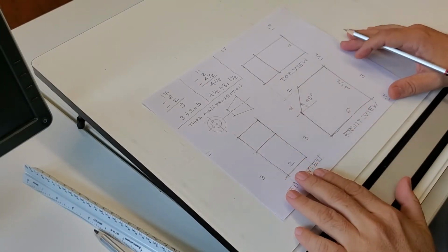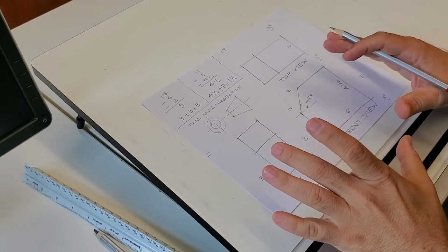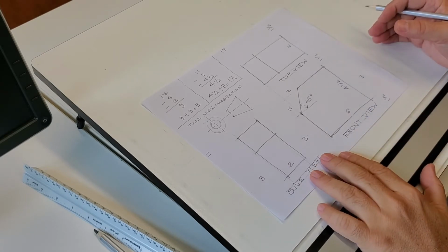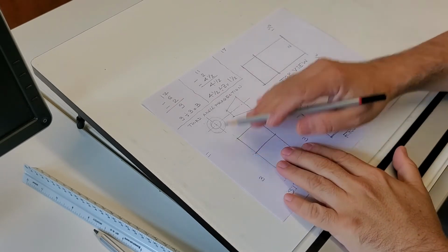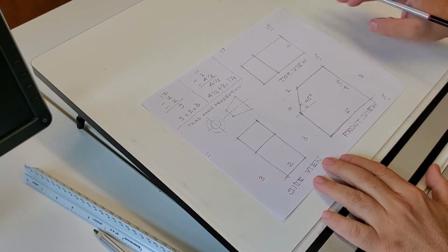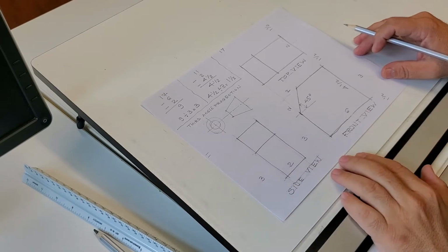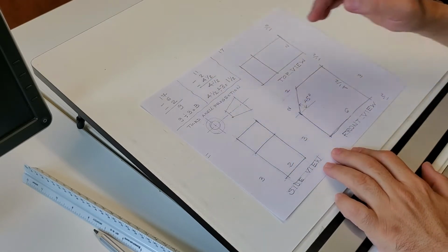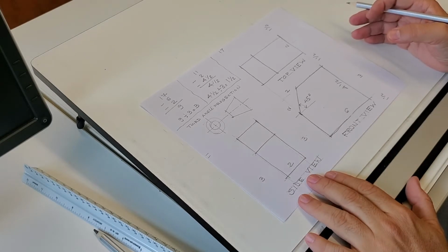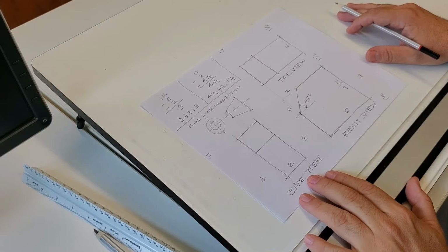In this sketch, I'm going to show you what we are going to do. This is a reduced size model, letter size paper. We will draw on 11 by 17 paper. We will draw only three views: the top view, front view, and the left side view. The arrangement is third angle projection, which is mostly used in North America. In Europe, the first angle projection is used.